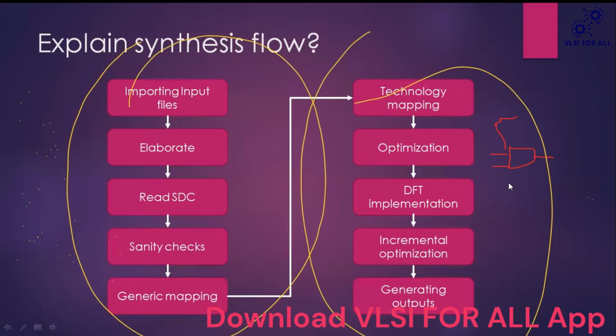After this conversion of normal flip flops to scannable flip flops, they will give that database again to the synthesis engineer. This DFT implementation is done by DFT engineers. Then the design is given back to the synthesis engineers. After that netlist comes back, we have to do another incremental optimization.